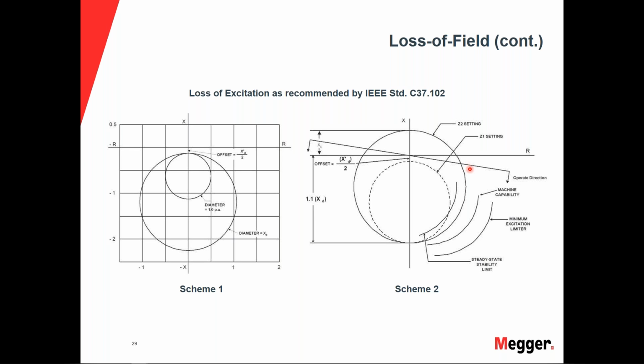When we use the typical zone 1, we're just going to have a very short time delay, if any, into this zone, but we're also using our zone 2 as our main time. So if our impedance comes into this zone, we want to make sure that we give our operators enough time to be alarmed and try to get this resolved, or if not, watch it, because it could come into the zone, alarm, and it can also come out. It just gives everybody in the control room an idea of what's happening and to be prepared if this does have a loss of field situation happening.